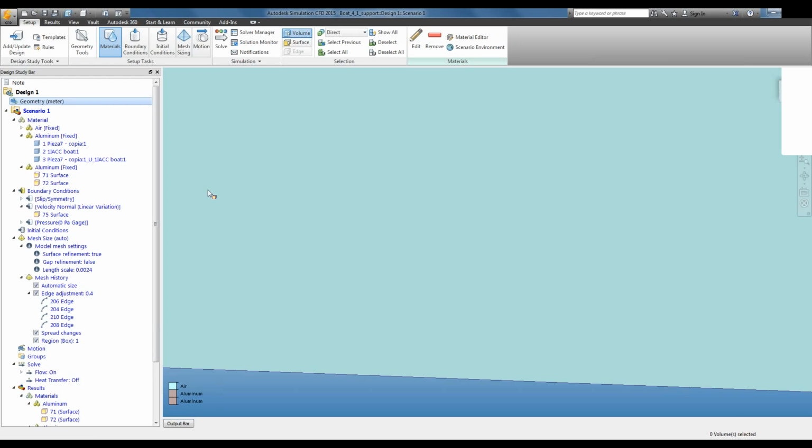I used CFD as external volume. I can specify exactly, wow, my boat's this long, I want my box this much longer, and use the two-thirds piece for the length: two lengths upstream, three lengths downstream. Create my box, and then I type in an angle, and then it's real easy for me to say, oh, instead of 25 degrees, I want 24 degrees. And you can really precisely do that.